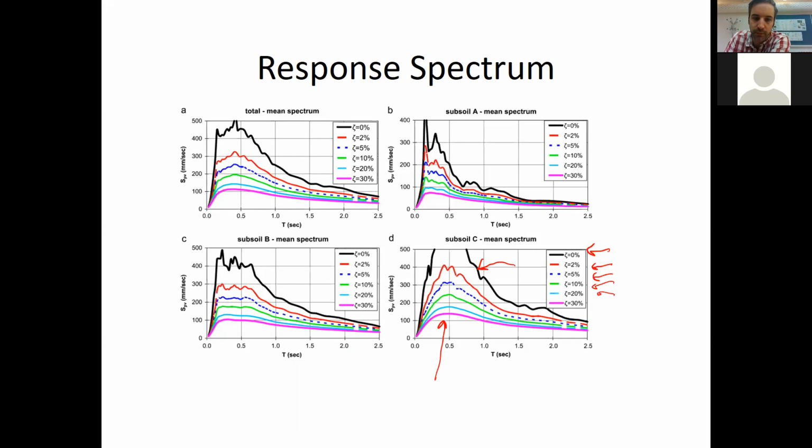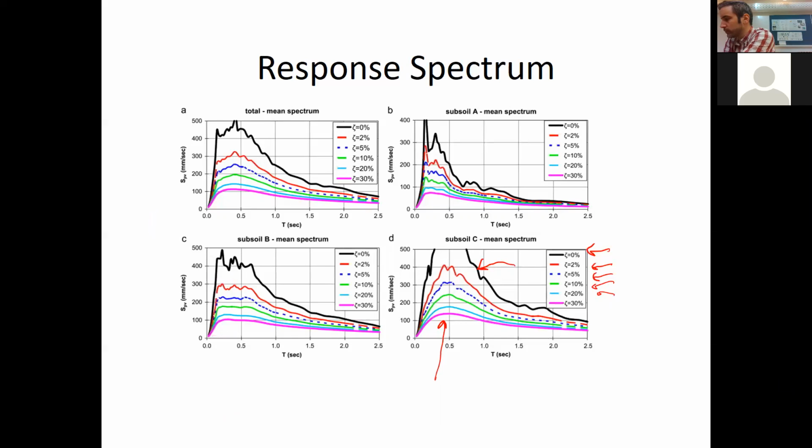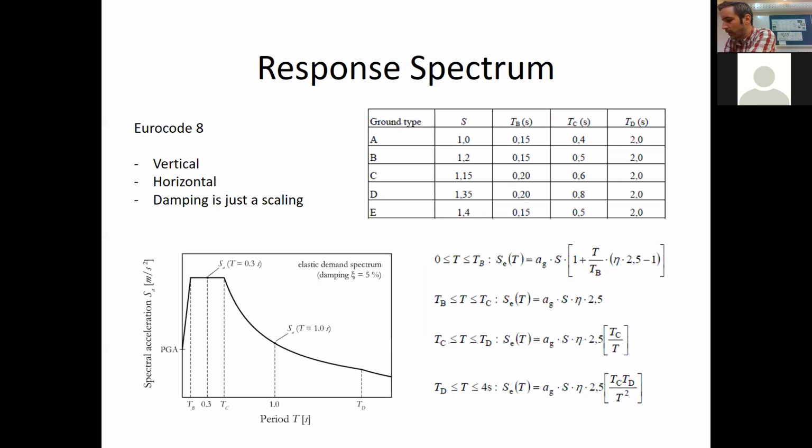That is just expected, right? The higher the damping, the lower the response. More realistically for a structure would probably be the red curve with a damping ratio of 2%, maybe 5%, it's also realistic. So a real engineering structure will behave somewhere within those two. Okay.